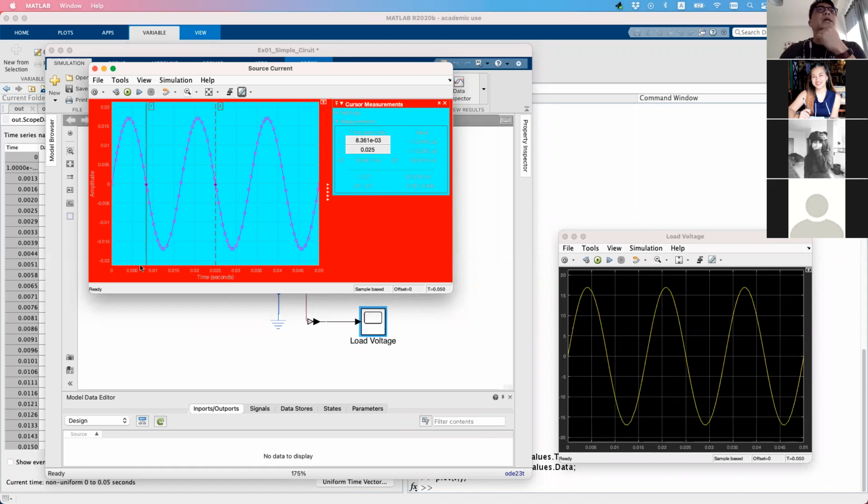Okay, by the way, when you were discussing, some of you in the video kept saying wavelength, so let's look at one wavelength. Well, actually, you use wavelength if the x-axis scale, the horizontal scale, is in terms of distance. But here, it's in terms of time. So what you use here is period. So you're referring to one cycle as 1 period if we're referring to a time scale. Okay? So you can see that delta t is 16.67 milliseconds. It immediately computes the frequency, so it's 60 Hertz.